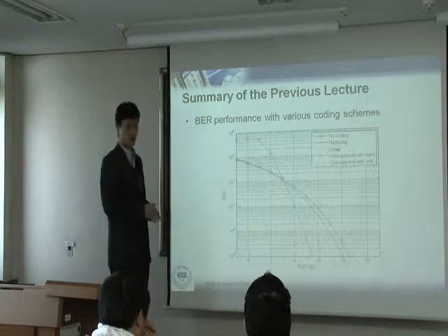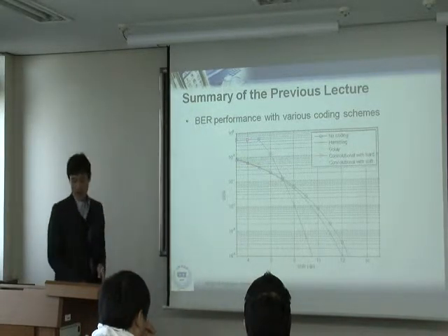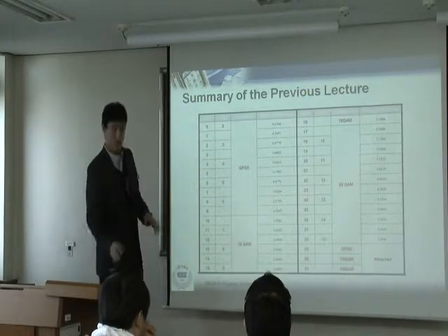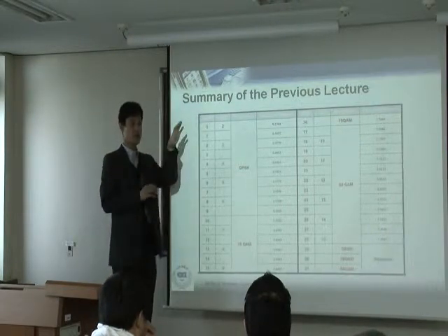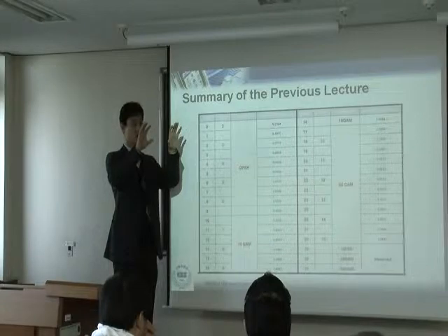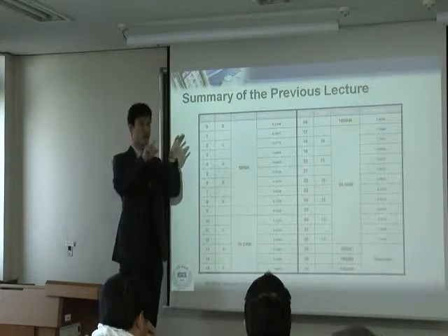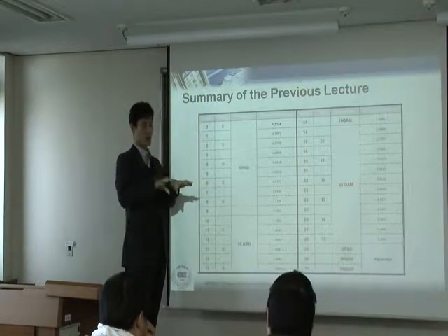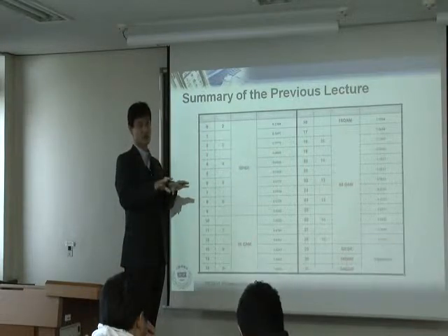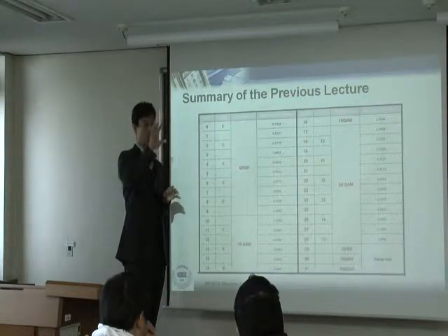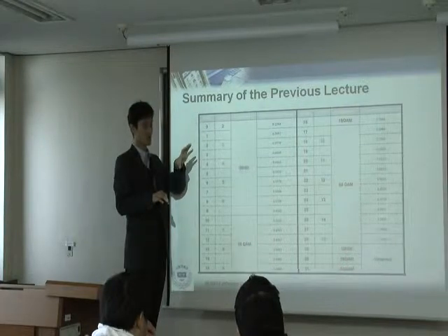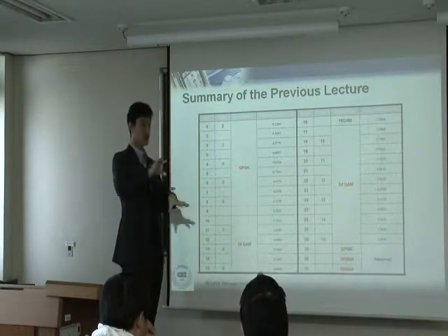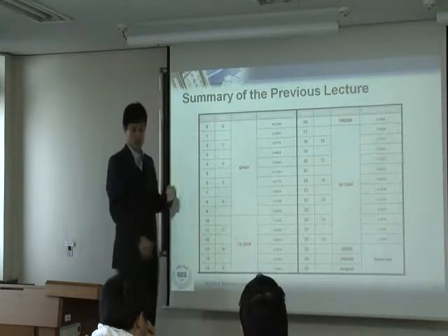So that's how an actual system does it, right? What an actual system really does is pull this together. You make a combination. For example, BPSK with convolutional coding with coding rate 1/3. Another case is QPSK with convolutional coding, a coding rate of 2/3. Things like that. You change the coding rate, and you also change the modulation, so you make a combination: this modulation with this coding rate, that modulation with that coding rate. You can make so many combinations like that.